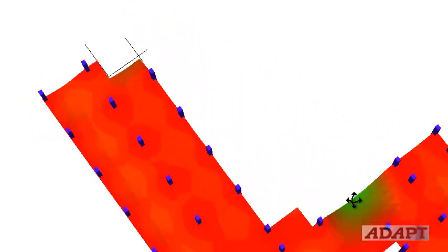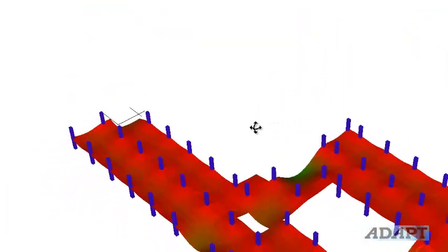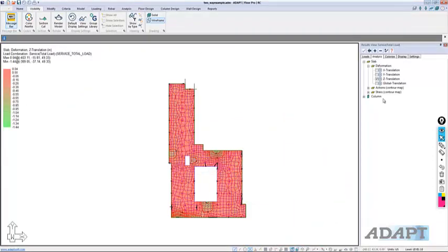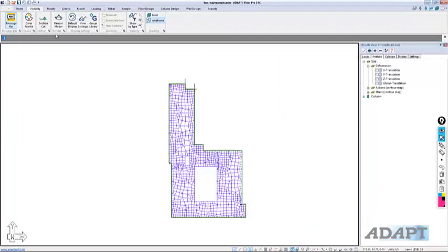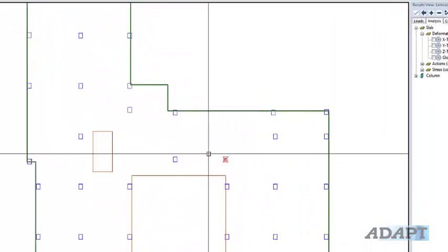There's kind of a hot spot over here also. I'll add another column there too, so we don't have these peak deflections where we're going to have severe locations. Realistically, this could be the real model, but we're going to go ahead and make that modification also. I'll go back to analysis, clear out the mesh, and let me just copy this one.